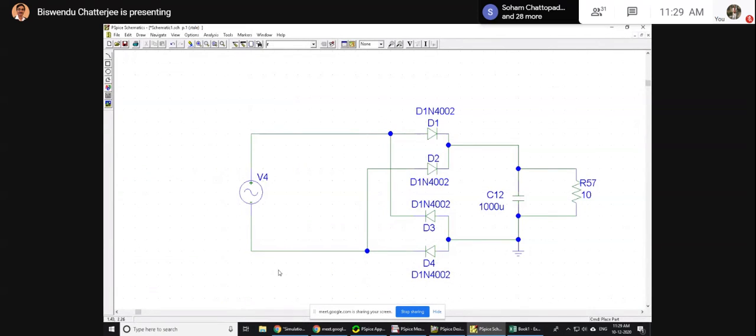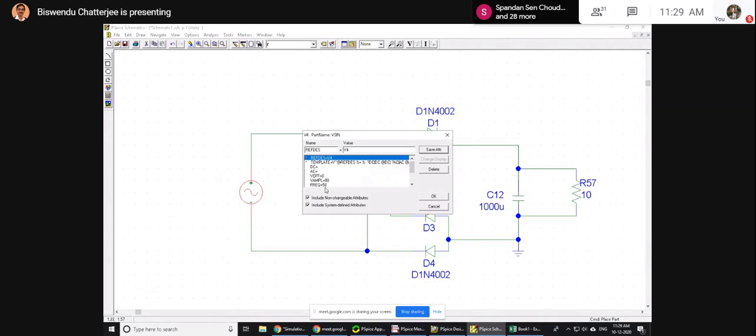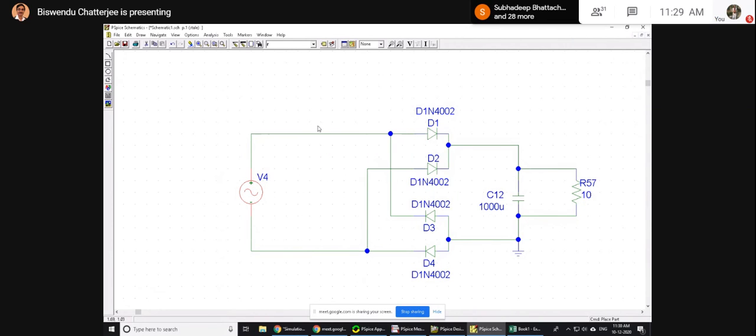Okay, now I have done this thing. Now, what is the voltage? For voltage, the markers mark voltage differential. It is not absolute voltage level, because, understand the things very carefully. See, where is the reference point? It is here after the bridge rectifier and filter.